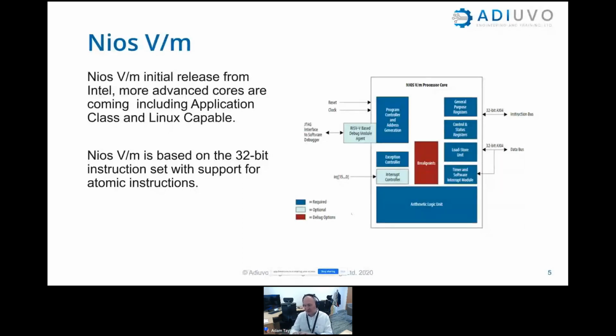Obviously, that doesn't incorporate the rest of the system. You'd have to handle where the addresses are for the peripherals you've put on there, and if you've put any special custom instructions in there that aren't in your Nios 5, you would have to address that. But in principle, it gives you a nice flexible solution for leveraging and building on this open source community.